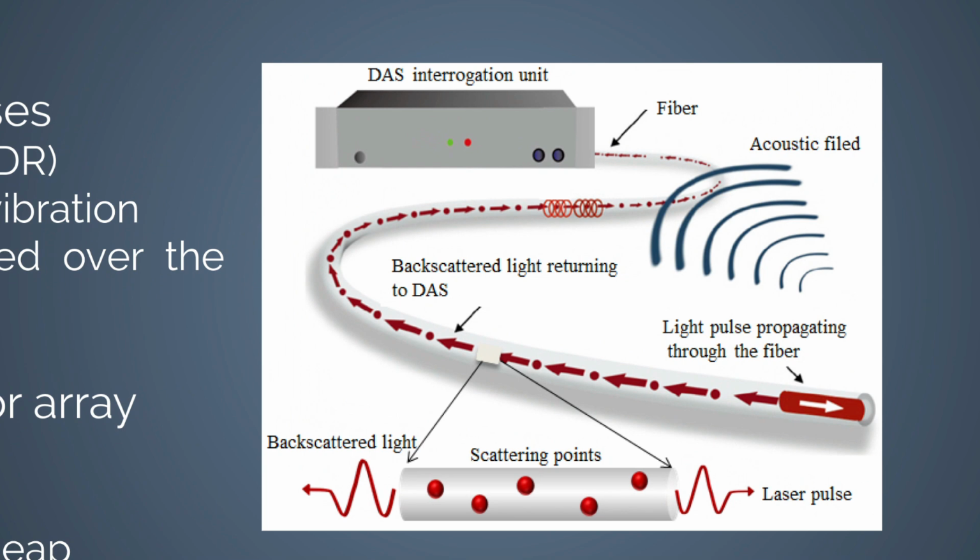The working principle of DAS is based on the elastic Rayleigh wave scattering of laser pulses in the optical time domain reflectometry. The laser phase is linearly proportional to the vibration, and the single component strain rate is averaged over the gauge length. Standard optical fiber acts as a sensor array, allowing for the measurement of small strain rates at a sampling rate up to hundreds of kHz. Additionally, the fiber is durable, and each channel is relatively inexpensive.